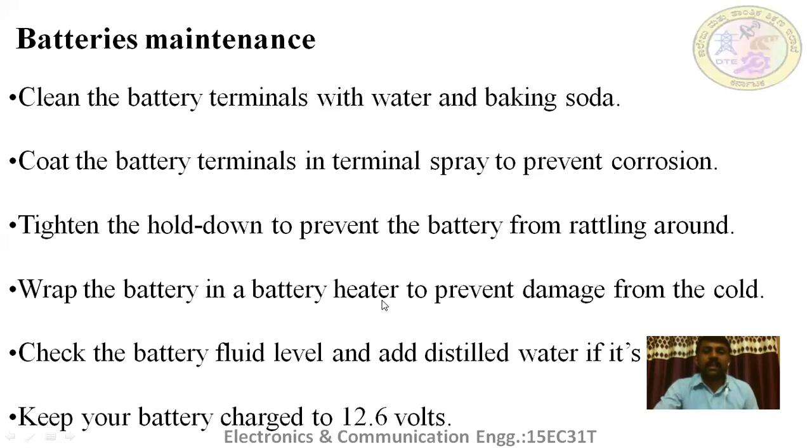Wrap the battery in a battery heater to prevent damage from the cold. So if you are using the batteries or inverter in an area of cold weather, it is required to cover the batteries with a box or some wrappers to maintain the temperature. Or if you are using the batteries in an air conditioning environment like in computer labs, there is no necessity. Check the battery fluid levels in case of lead acid.